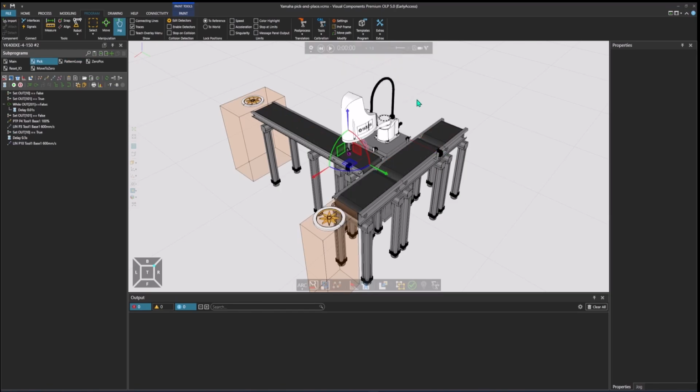And at this point, let's disable the robot executor. It can be found from the robot properties under executor. It is because we want the control hub in the end to be on the RCX side, so that the Visual Components program does not control the robot itself.